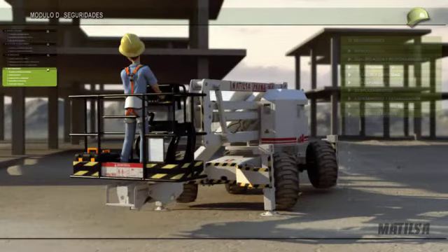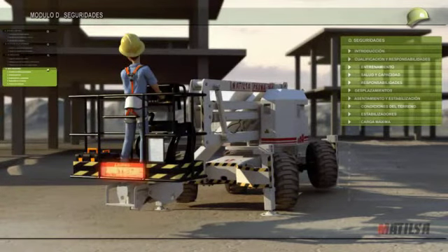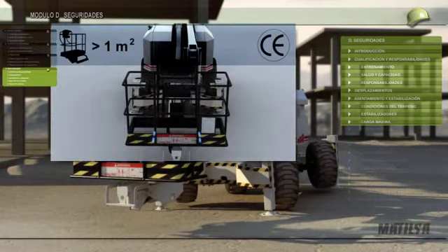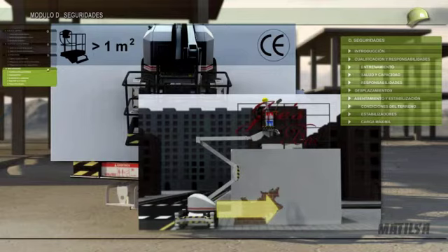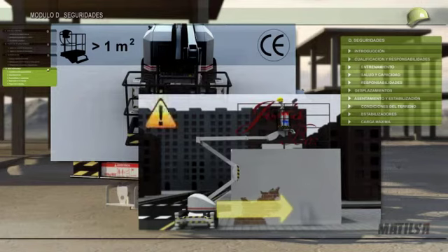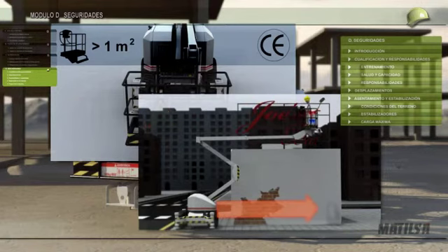The maximum permitted load on the platform must be the one indicated by the manufacturer. This maximum load includes people and their tools. If the platform loses the maximum load device, then we will make sure we turn it back on before gaining access to the platform. If the platform is bigger than 1 square meter, then it should carry a loading device that prevents access. In this case, it must not be manipulated to allow the elevating of more than the recommended load. Warning! Excess weight may cause serious accidents on the structure of the machine. For example, when we do the maximum possible sideways transporting.